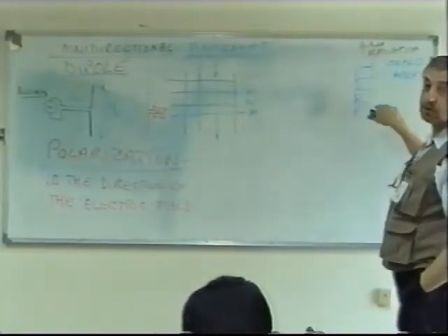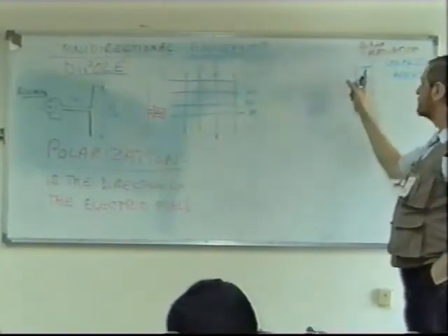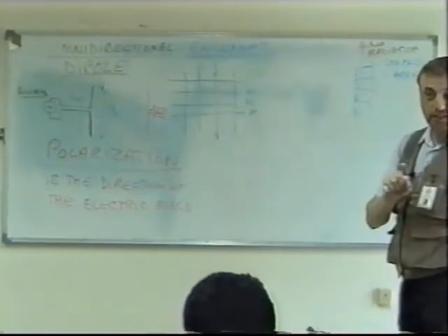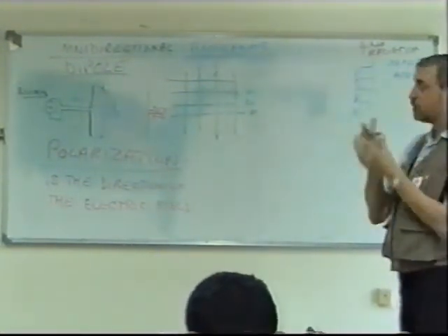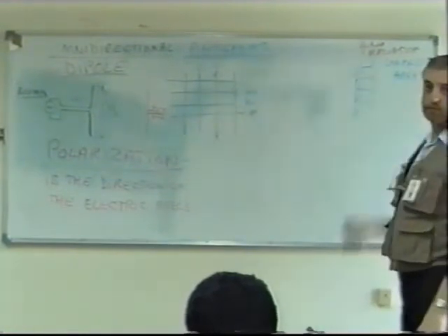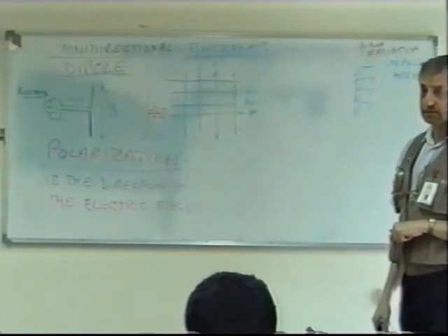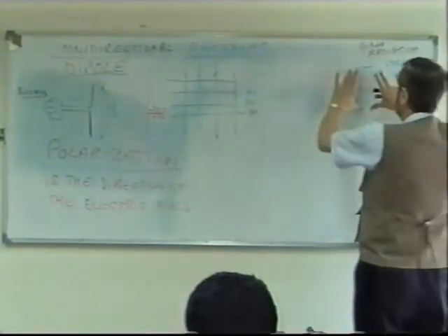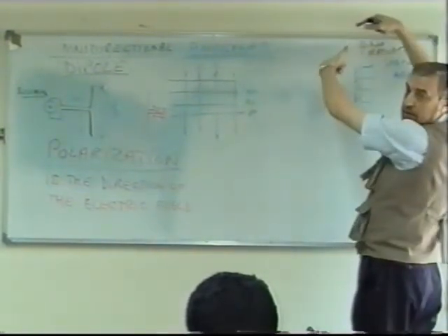In other words, how does this work? Yeah. Well, what actually happens is when we supply power to each of these from the same transmitter, the phase at which we supply the power changes between each of these dipoles. We don't supply it all with the same phase. The phase changes. The result is there's more radiation from the middle and less radiation going up.